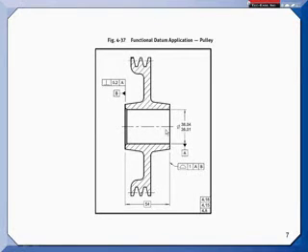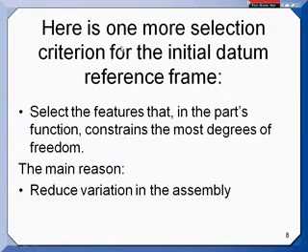And with the pulley also, the bore is made the primary datum feature, constrains 4 degrees of freedom. This shoulder is going to take away 1 degree of freedom, so they called that the secondary datum feature, B in this case. So those are my interfacing mating surfaces. But I had another interfacing mating surface up here that isn't a datum feature. Sorry, I jumped a little fast there.